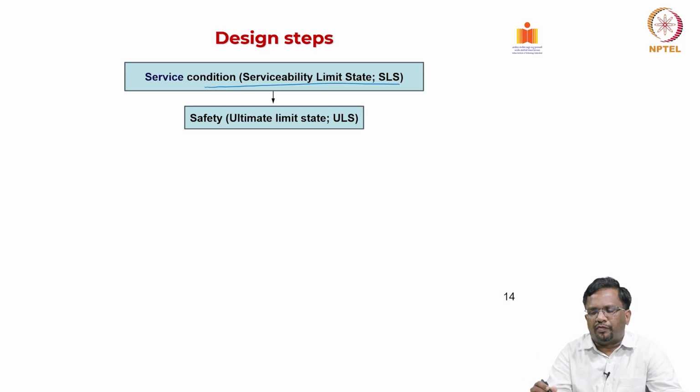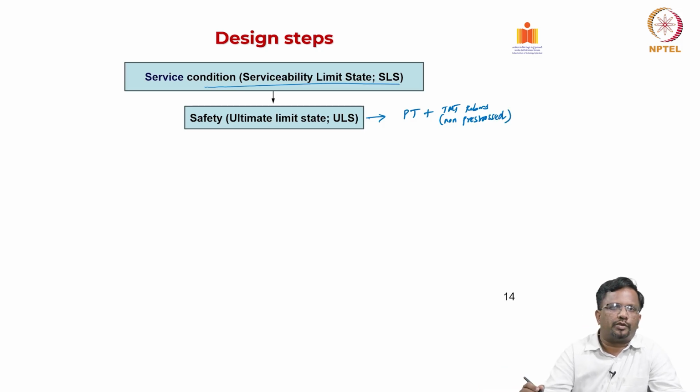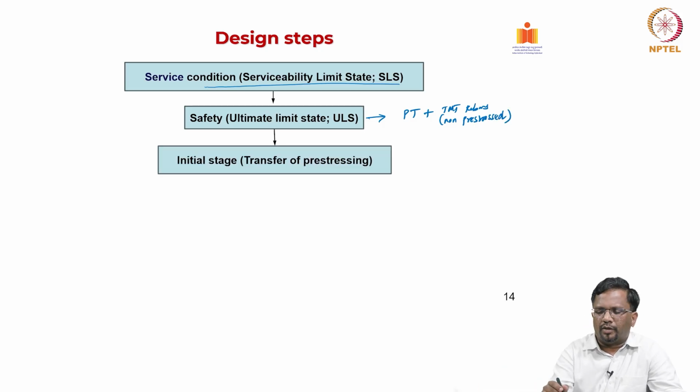If PT alone is not sufficient, then I can put PT cable plus some TMT rebar. The TMT rebars, as you know, are also called non-pre-stressed rebars.